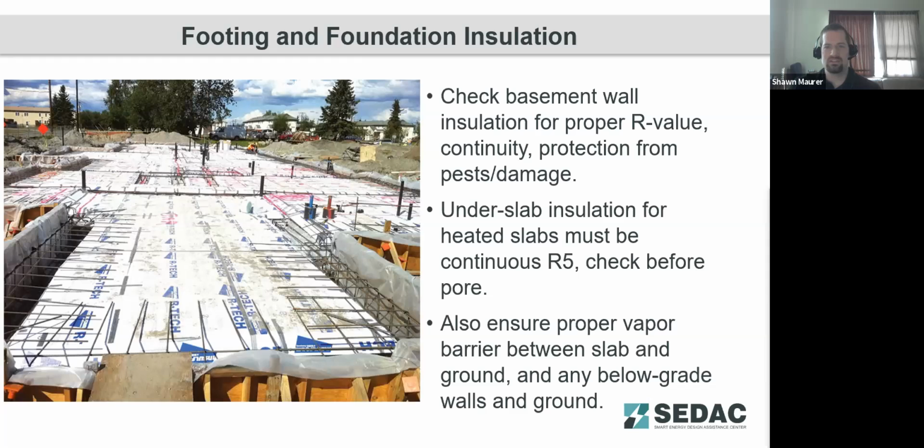So footing and foundation insulation, for basement wall insulation, you're checking for that proper R value and continuity, and protection from pests and damage, particularly if that insulation is on the exterior of a foundation wall. For heated slabs, if you have under slab insulation, or if you have an unheated slab where a component of your insulation is wrapped underneath the perimeter edge, that insulation needs to be inspected and verified to be the proper depth, proper R value.